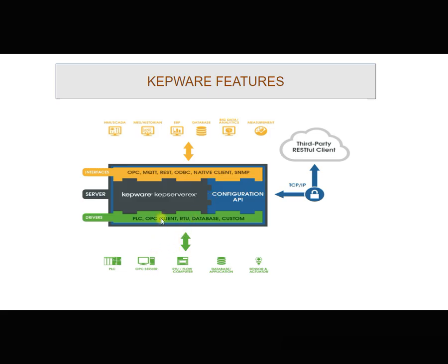Whatever data you are getting from the PLC, the supporting drivers will be at the base level, and a suitable conversion API has been written in KEPServer. It converts the data into a suitable form so that you can operate these devices at the interfacing side. So KEPServer is one of the software we use to convert the data you are getting from different brands, which you want to connect to different brands of SCADA.